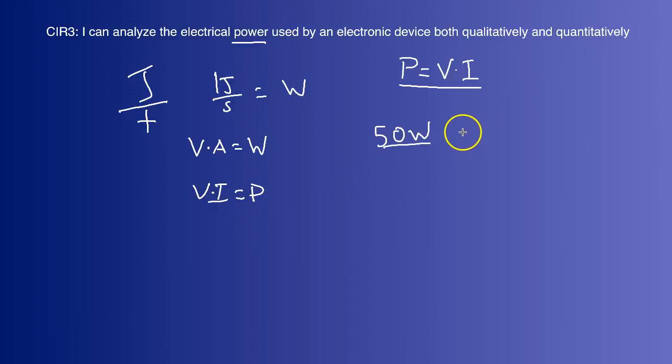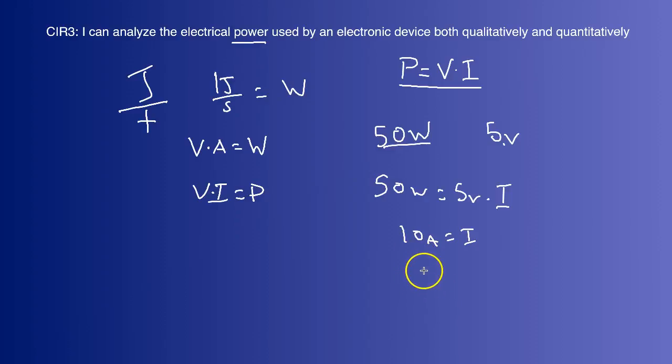And since it's charging through USB, well, USB is 5 volts, okay? So if we have 5 volts and we have a capacity of 50 watts, then how much current do you think we could produce? Well, we could say 50 watts of power is equal to 5 volts times our current. And so what this means is, if we divide that over, 50 divided by 5 is 10 amps. Okay, and that's a lot of current. So if you're charging a phone at its maximum capacity, that's about 2 amps. So you could charge 5 phones really quickly with this, or you could charge 10 phones slowly with this, is basically what the capacity of that charger is. Okay,